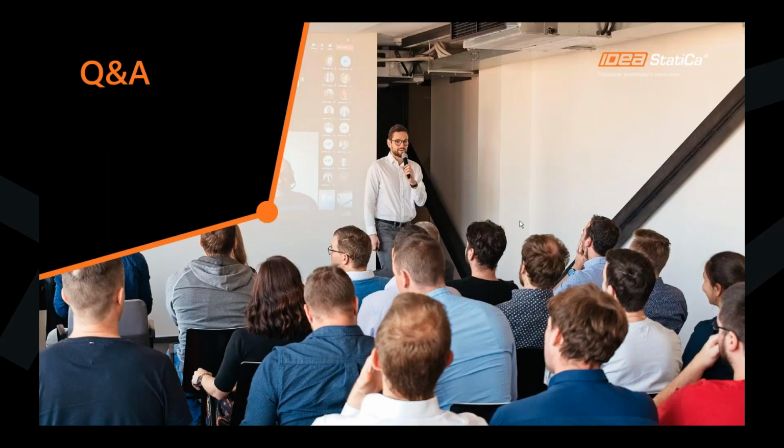Okay, it's from Nasim. Can IDEA StatiCa check bursting requirement? The bursting requirement in the strut and tie is actually considered using those K factors that I've shown you, 0.6. And as I've shown you, our solution can actually calculate the K factor automatically so that you don't need to calculate the reduction factor yourself.